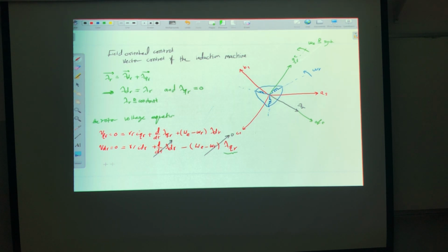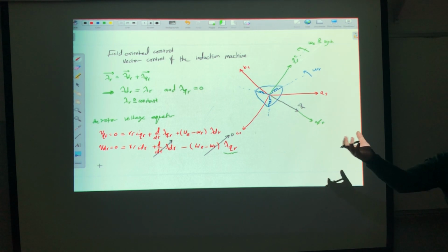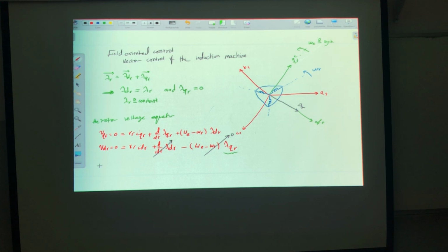So in the end of the day, because I'm assuming that the VA, the VB, the VC of the rotor are 0, so VD and VQ of the rotor will equal 0. Short circuit, or squirrel cage induction machine, one rotor shorted or a squirrel cage. So from here I can get that IDRE will equal to 0. Why here am I adding E? Later on I will not add it, to say that this quantity is described in the synchronous reference frame. Good?